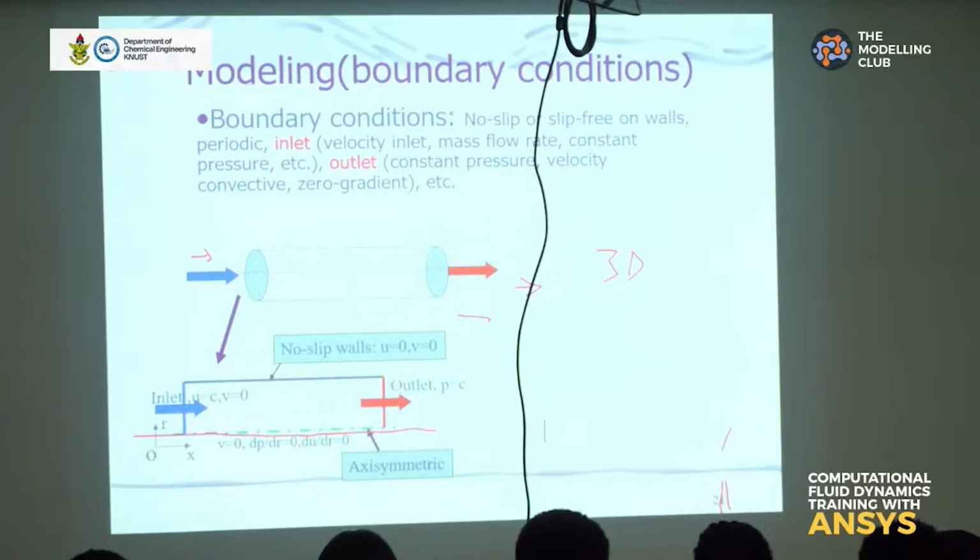Well, this is the v velocity, not u velocity. Inside the pipe, there is velocity variation in all directions, but the vertical component is 0. So that's a good question, good point. And similarly, the pressure gradient at that point is also 0.